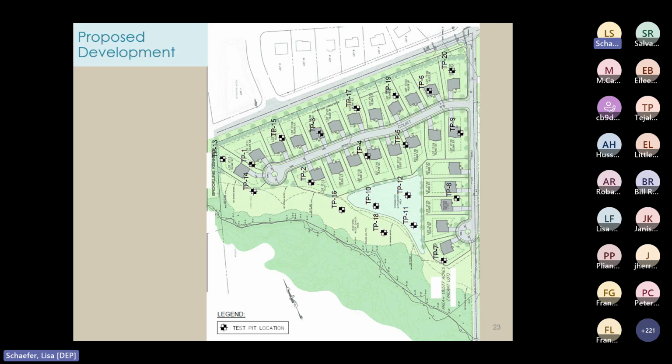But the reviewer would also want to check that for the revised design, the proper number of test pits and soil borings were performed. Now, in this case, the soil testing report was not revised to meet the testing location requirements for the updated multi-basin layout. So anyway, from the test pit findings, the seasonal high water table was determined to be at depths between 3 and 6 feet, mainly because mottling was observed.